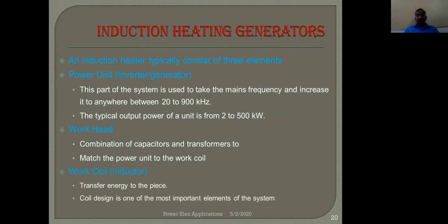The work coil transfers energy to the workpiece, actually the metal element. The design of this coil is the most important part because this determines the energy transfer. Inductor design is always quite crucial in most applications of power electronics, as we know. So this work coil is also one of the critical parts.